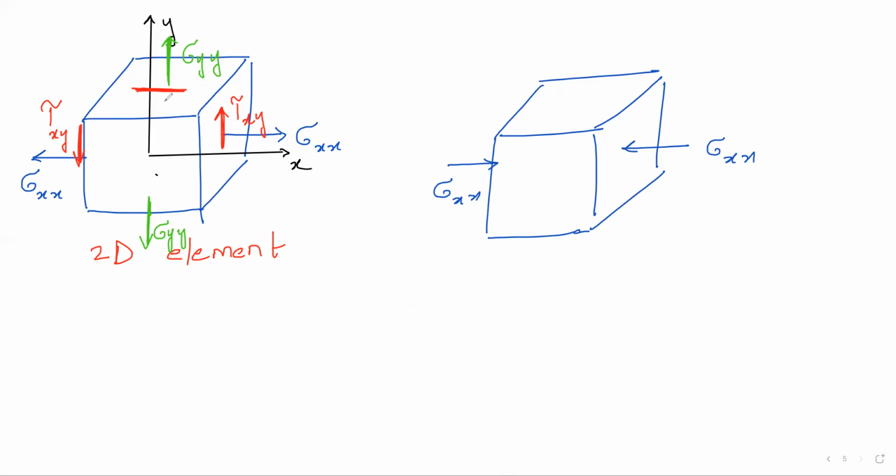We still have 10 minutes, right? Okay. I will actually make it like this and then you will answer everyone. Why do I have to make the arrow of tau YX like this? When tau XY is anti-clockwise, then these two arrows will be clockwise because of static equilibrium, right? Because you don't want this cube to start taking rotations. It's not possible. It's a static structure.